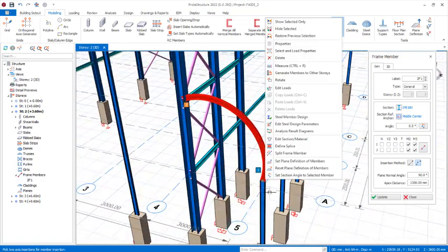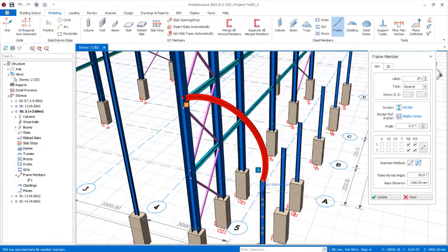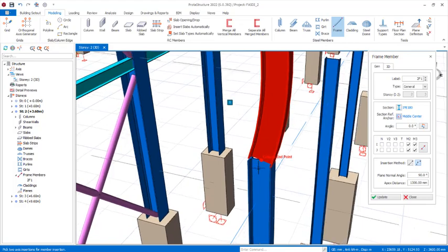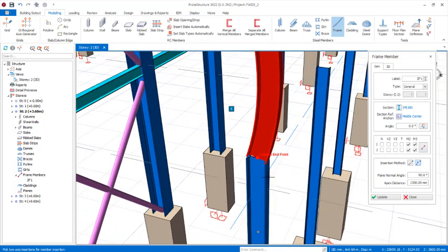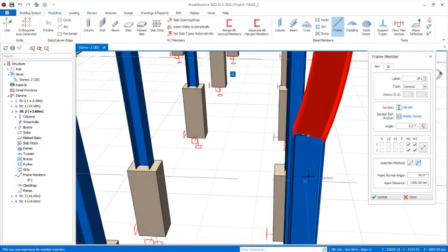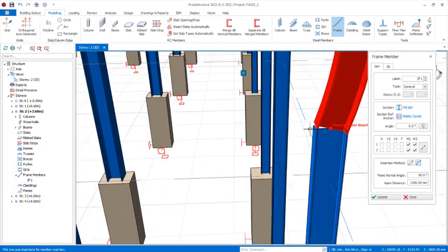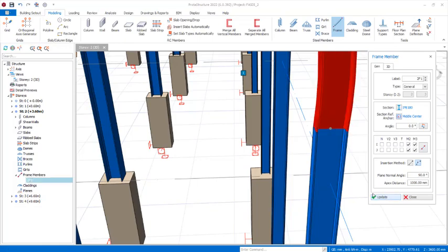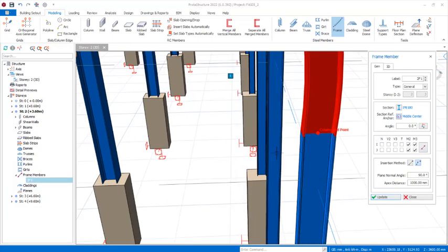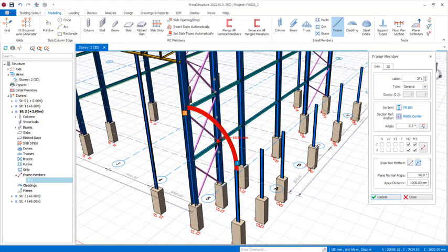You can see, but if you zoom in closely now, you'll notice that this curve beam has not seated rightly on top of the vertical stanchion. For you to make it sit right there, you need to come to these provisions and keep adjusting this. Let's say 1000. If you put in 1000 millimeters right here and click on update, you can see it has sat right there. So this is what I actually expected. All right, so this is what we are having.